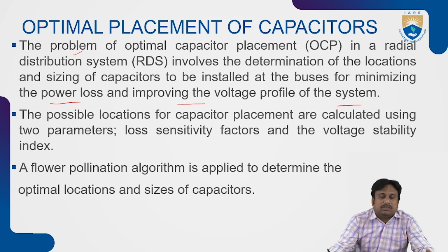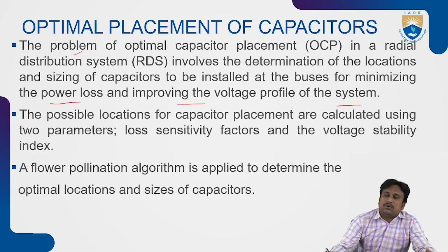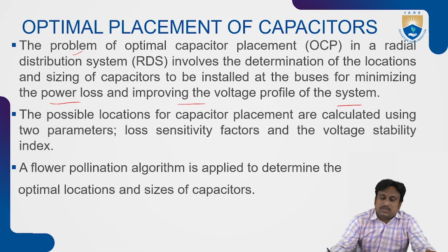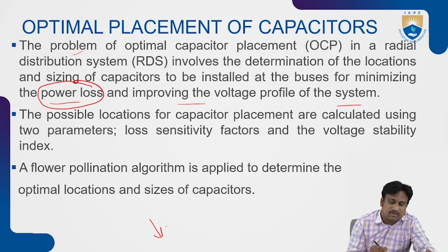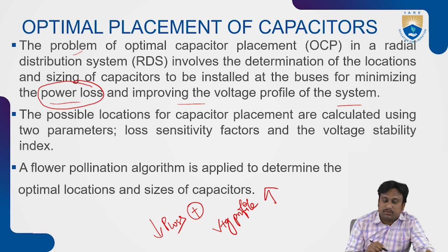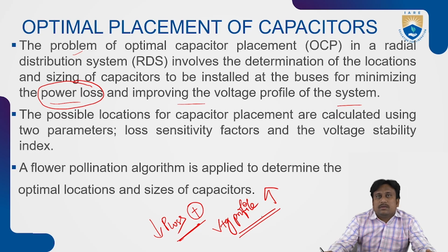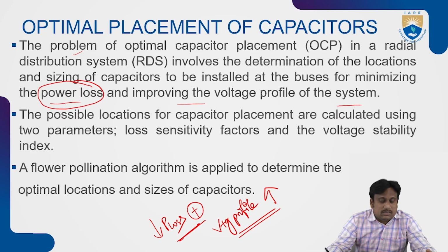It determines the locations and sizing of the capacitors at each bus, meaning at the respective substation, to minimize the power loss. This is the main advantage, and it also improves the voltage profile. These are the two factors achieved by optimal placement of the capacitors.